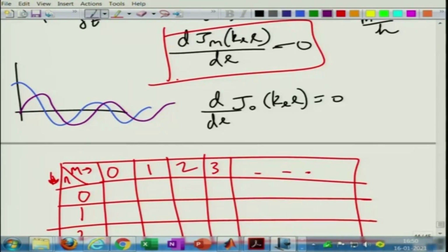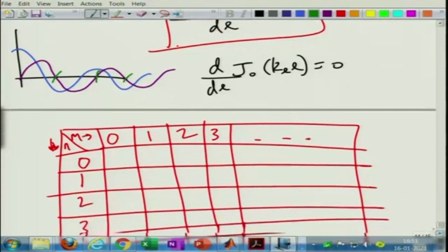So, that is again consistent with our analysis that if you set k_r to 0 and m of course is 0, then k_z will be equal to plus minus k_0, or the plane wave mode. So, regardless of whatever shape you deform the rectangular waveguide into, if you do not line it with any materials and this is a rigid wall, then of course your plane wave will always be there if there is no dissipation involved. Now, of course, if you go up, you have your first root here, here, here. These are all your radial modes.